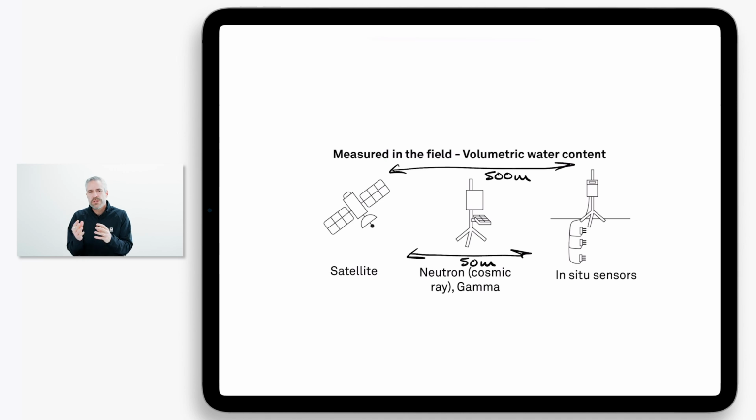One of the challenges with these systems is the depth that they measure. For example, a neutron system sometimes measures around 20 centimeters deep in the soil if the soil is wet, but can extend all the way down to 70 centimeters deep if it's dry. A gamma system maybe can only read 5 to 10 centimeters in the soil. So they have their limitations. The good side, you don't have to dig soil pits. You don't have to dig installation holes. The bad side, the accuracy may not live up to quite your expectation.